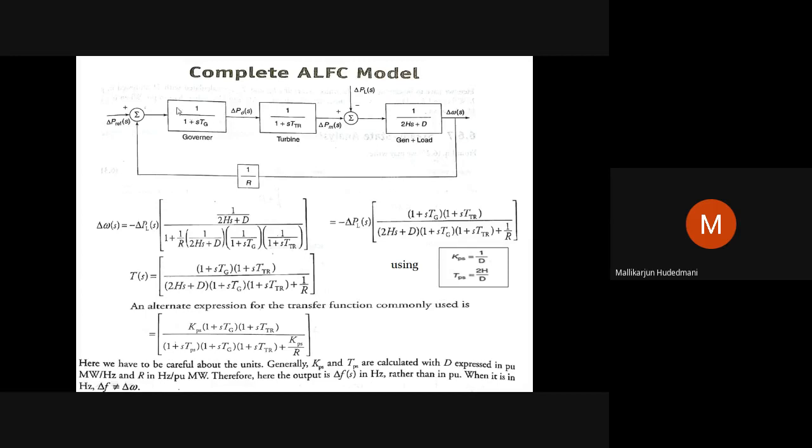This way, the governor will shift this error as a change in set point to a displacement. This displacement will correct the turbine output here. This turbine output and load, whatever has changed, the difference of these two acting on this transfer function, changes the error to 0 or keeps it deviating. Therefore, this is how in this block the deviation in frequency is continuously monitored and fed back to the system to drive this deviation to 0.